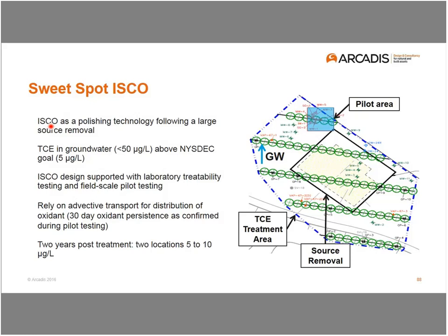And I'd point out that at 2 locations, which I'm showing here and here, there were monitoring wells downgradient of the transects to monitor the persulfate concentration as well as treatment. So we were able to confirm the distribution in the field, and ultimately this achieved a regulatory endpoint. And it's important to highlight that this is an implementation of ISCO in a sweet spot because it was implemented alongside a source zone strategy. There was focus on achieving meaningful distribution. There was an implementation over the full dissolved phase plume. And it was completed within a regulatory framework that allowed some flexibility with respect to the end game.